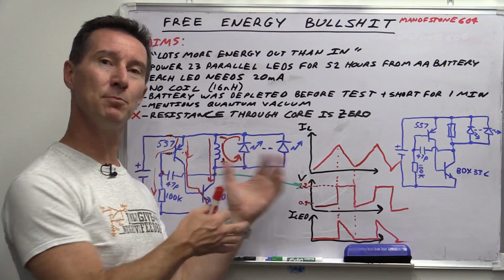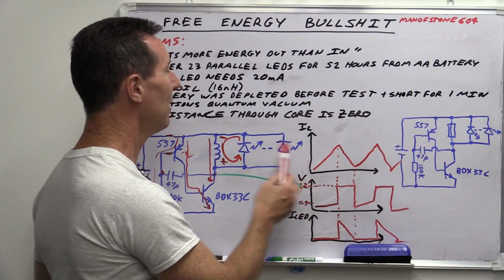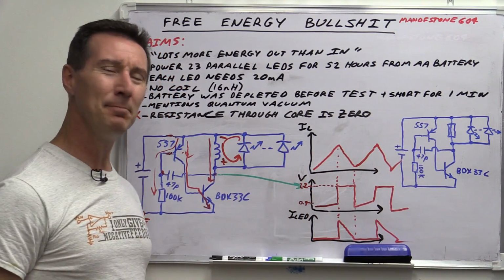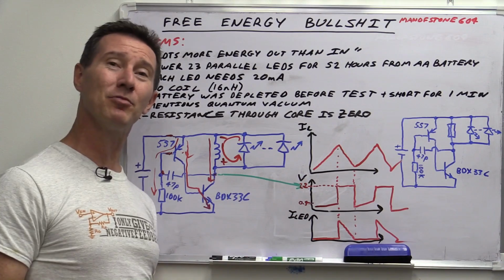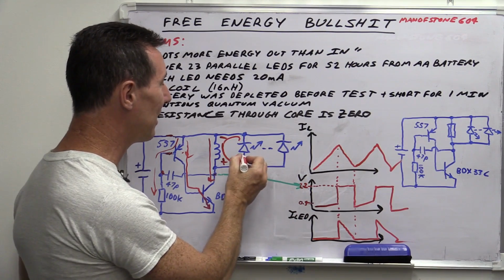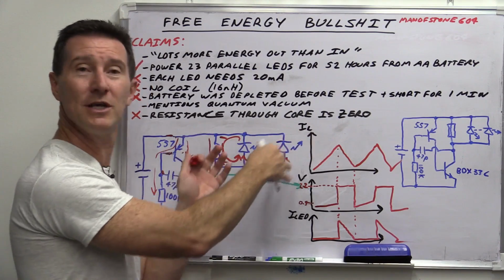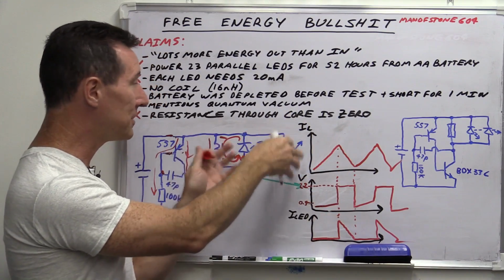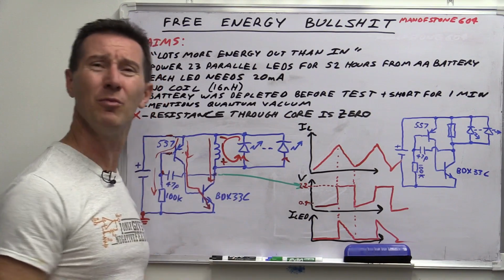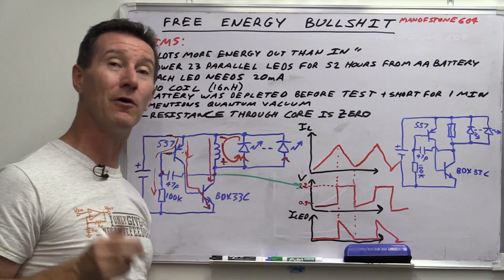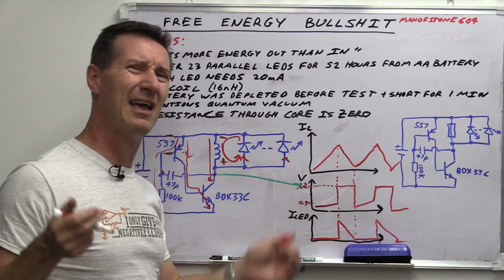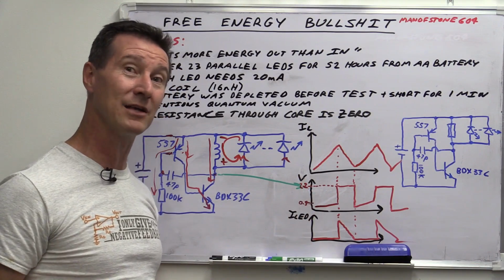And of course the other piss poor thing with this circuit is that we've got all the LEDs here in parallel, and you just don't do that in professional designs because they're not going to evenly share the current. It's going to depend on the process matching of the particular dies and everything else. It's just a horrible way to do it. It's totally uncontrolled. But yeah, it works for a hack circuit.